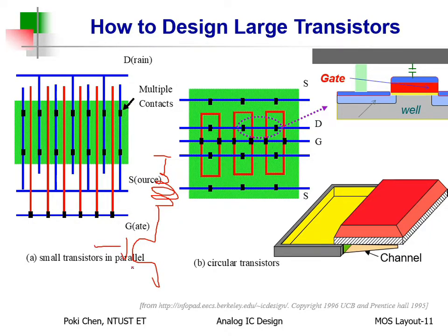Oh, bingo. That is what I want to share with you. The transistor is on the floor, right? But the inductor is on the top layer. They are far away. So in this way, this metal wire can go from metal 1, metal 2, all the way to top metal. Then go to connect the inductor. Got it? That's it. Okay?